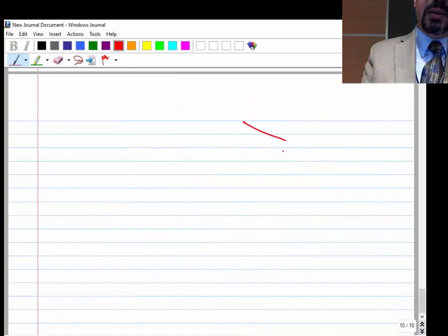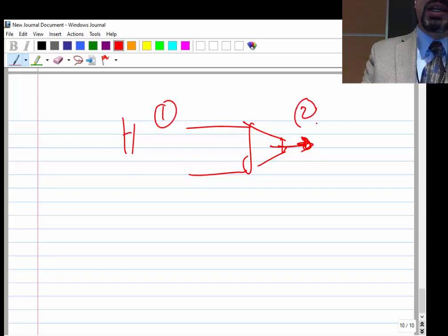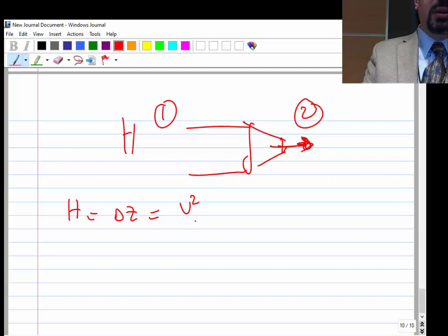Of course, that nozzle will have losses in it, right? Then they will give you the loss coefficient, just like a pipe or this reduction elbow have losses. But assuming you got this H and here at 1, and you are basically sending everything into kinetic energy, if you apply Bernoulli equation, you figure out that H, which is the delta Z across the nozzle, will end up being all V2 squared over 2g.